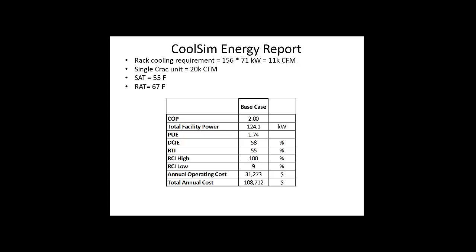That's not a great number. 4 would be better. The chillers often run in the range of 4 for every kilowatt they reject of heat. They require about 250 watts to drive them. That's a fairly good ratio. This one's not a good ratio. It's 2. These are often a result of being DX units, but also this one's got a very poor return air temperature as well. So that is an estimate.